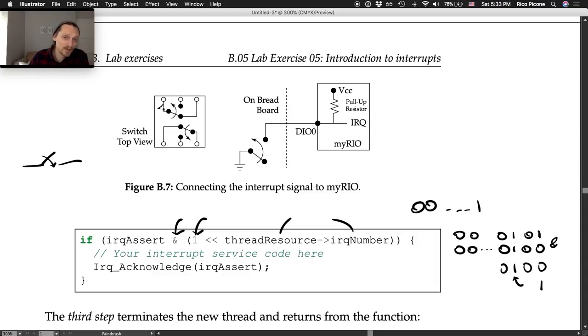But what we're going to do is, we have to be careful of, in the breadboard, when you put it in, it actually connects these. So what you do is you cheat and you bend. I just bent. You can actually cut it off, but you bend one terminal like this, so that when you connect, if you bend this one up, then no matter which one you connect, this is a dead end, right? So open circuit. So you bend the one, or you cut the one that is connected to the base of the switch. So that's what I did. Otherwise, you would have not the circuit that you thought you had, I guess.